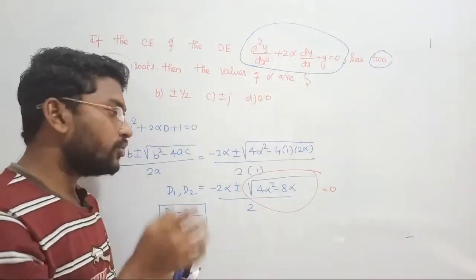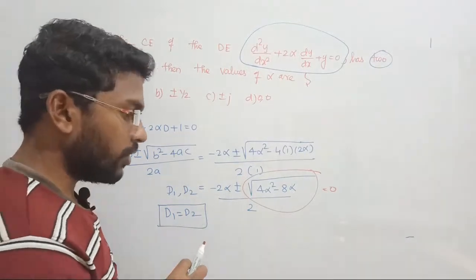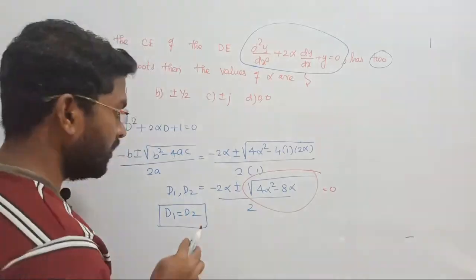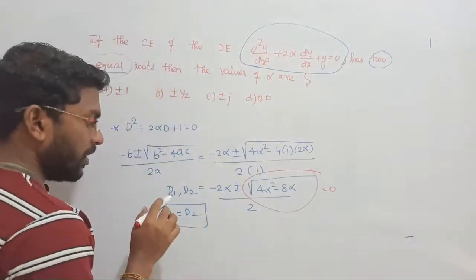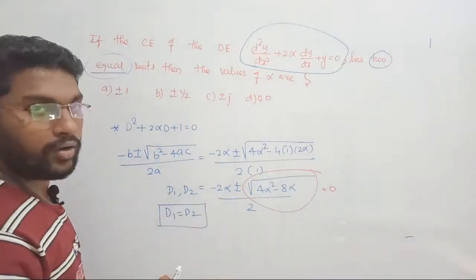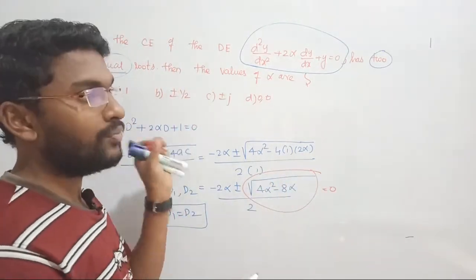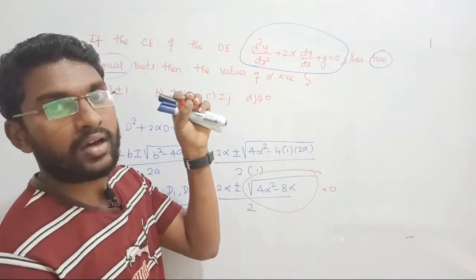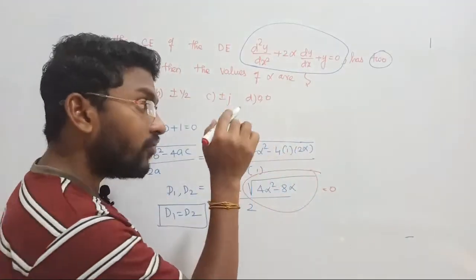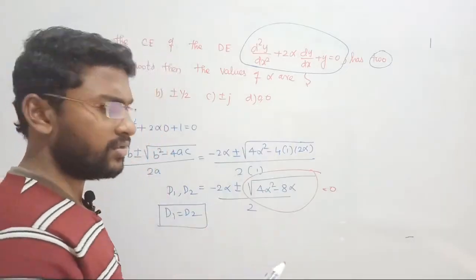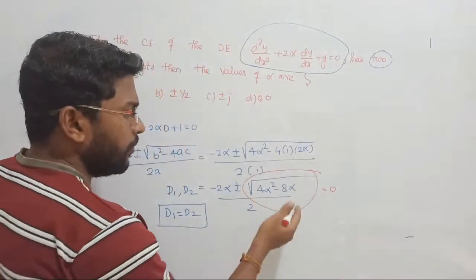Yes, right? So given it is, what they are talking about is the critically damped system, right? So according to that condition, for the critically damped system the 2 roots to be equal, the imaginary part is completely 0. In critically damped system also you might have observed there are 2 roots, right? They are real roots, they are being placed in the left half of the S plane. Just you can go through our second order control system notes, right? So imaginary part is going to be 0.